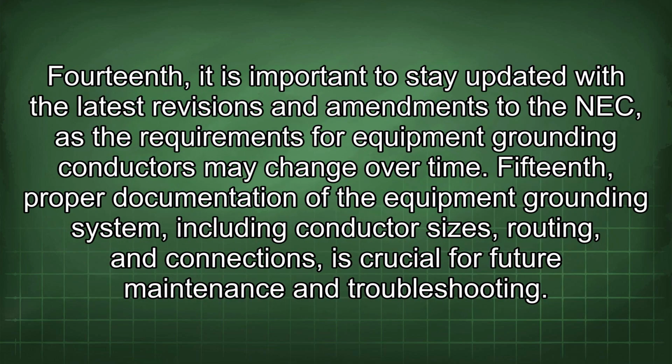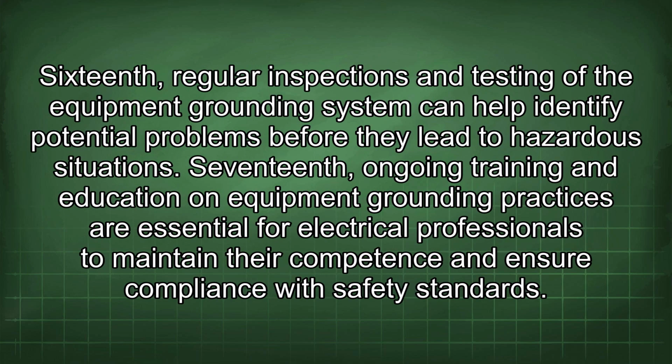14th, it is important to stay updated with the latest revisions and amendments to the NEC, as the requirements for equipment grounding conductors may change over time. 15th, proper documentation of the equipment grounding system, including conductor sizes, routing, and connections, is crucial for future maintenance and troubleshooting. 16th, regular inspections and testing of the equipment grounding system can help identify potential problems before they lead to